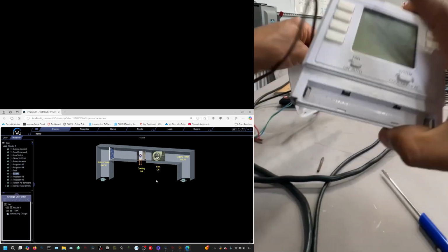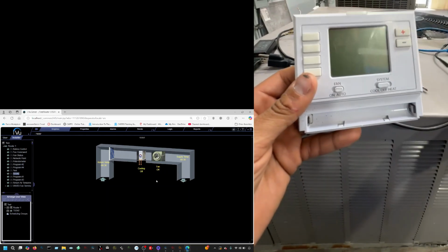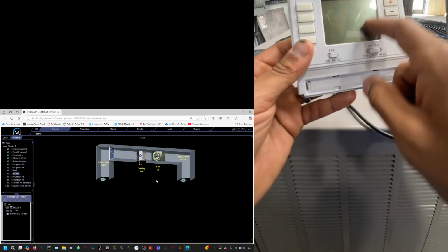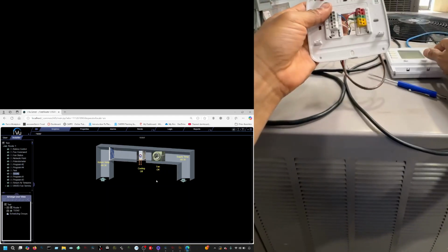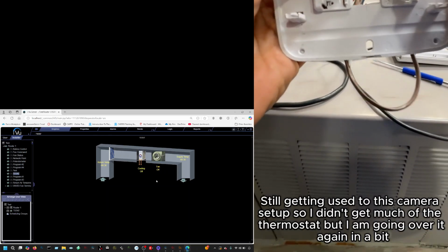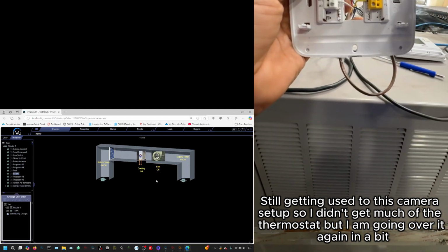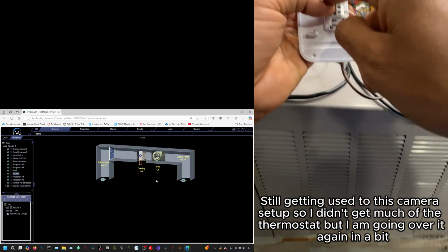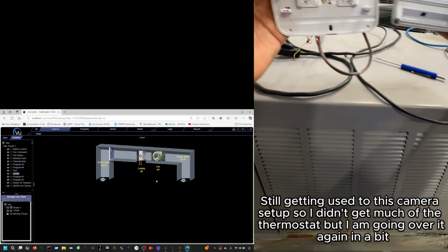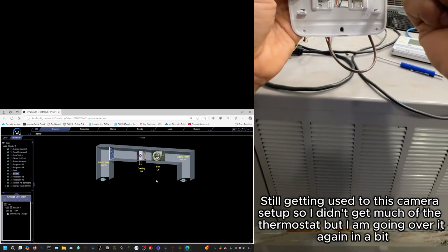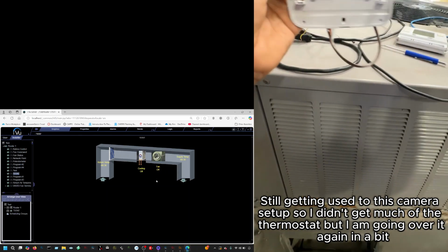All right, this thermostat, a lot of the times, if you're working with a heat pump, you actually have to tell it that it's a heat pump by going to the advanced settings. But can we agree that all the thermostat is doing is receiving 24 volts here, and if I have a call for cooling, now keep in mind it's a heat pump, so it needs to send 24 volts to my Y and my O, right? So what it does internally, the R is like, here you go, and it gives 24 volts to Y and to O, and that's cooling.